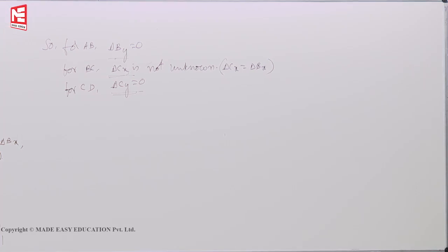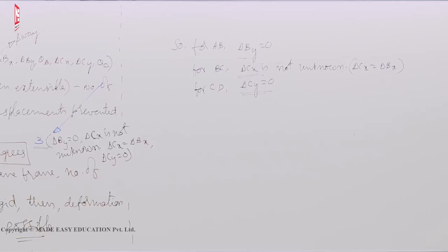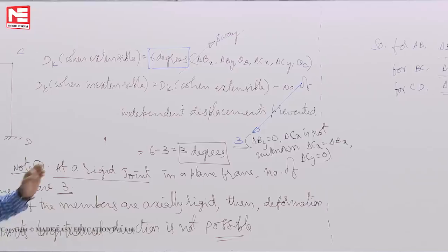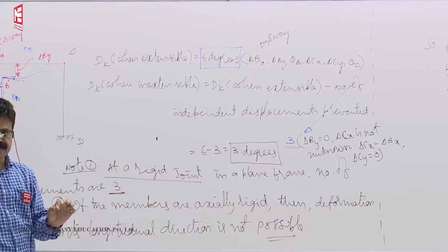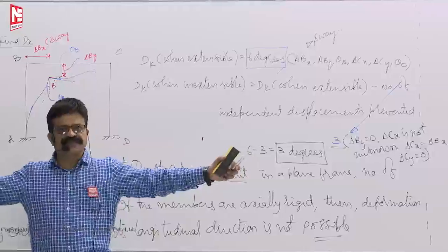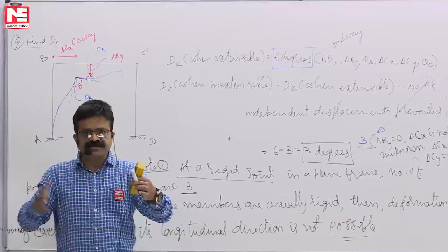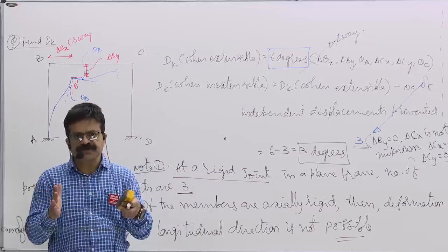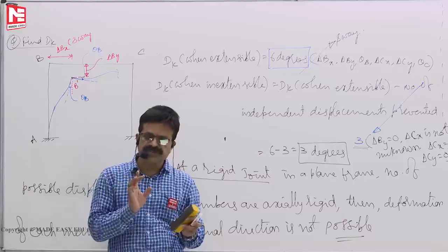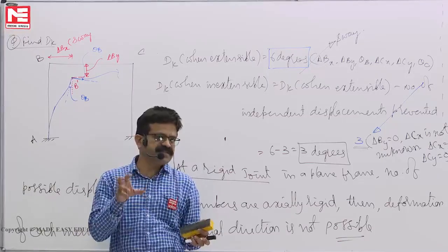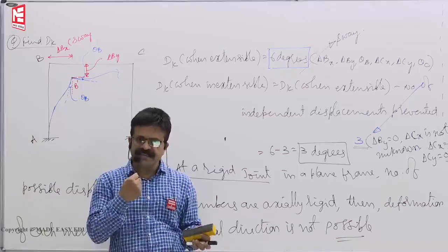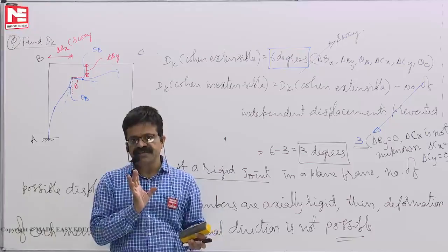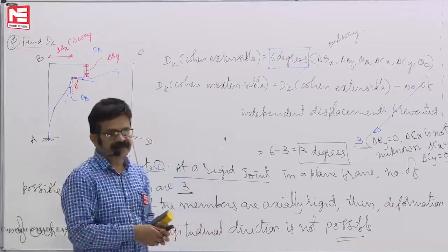Now, let us add bracing. Bracing rods are not part of the structure we should count. If they are given as bracing rods, say the length of a rod is 5 meters. Under compression the rod buckles, and it can take only a very little compressive force. So we assume that the compressive force in the bracing rod is such that it is ineffective. Only the one bracing rod which is under tension will resist the sway of the frame.